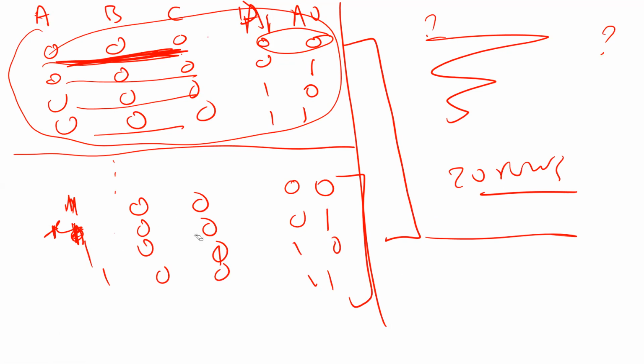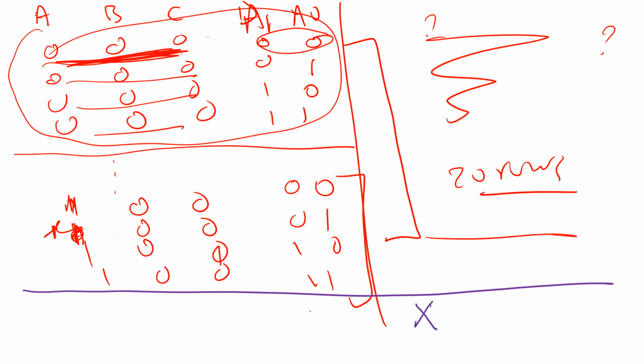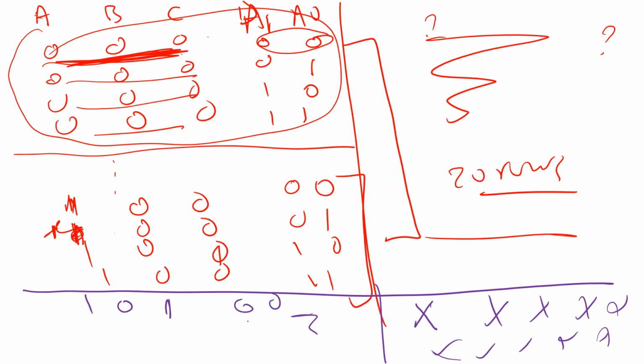Now, after this state, I'm going to tell you here, using a different color. Anything after that, all you have to do is put the input and then just put don't care, because this shouldn't happen. For example, we don't have state 5, since states go from 0 to 4. In these 4 cases you still need to consider the 4 input cases, 0, 1, 2, and 3, and for these you just put don't care.